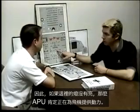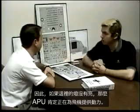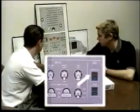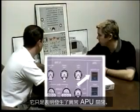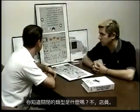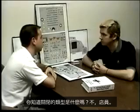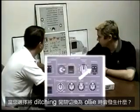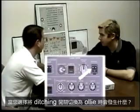So with an absence of the on light here, the APU must be powering the aircraft. What about fault in the APU master switch? It just indicates that an abnormal APU shutdown has taken place. Do you know what type of shutdown has occurred? No clue. Ditching switch. What occurs when you select the ditching switch to on?